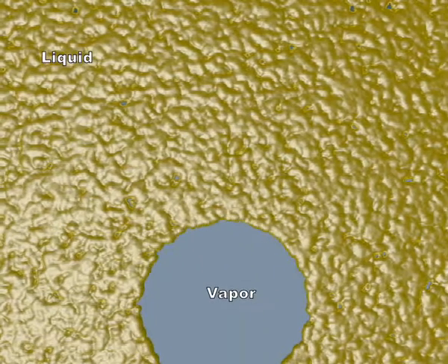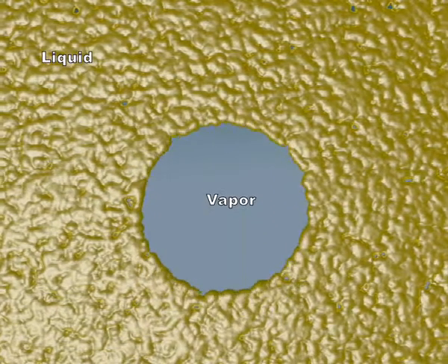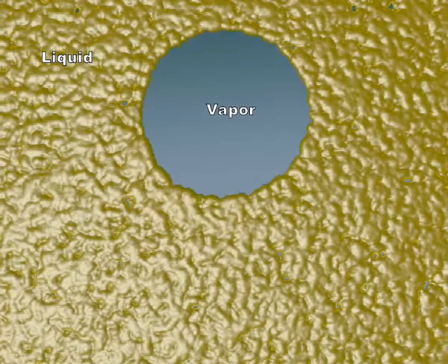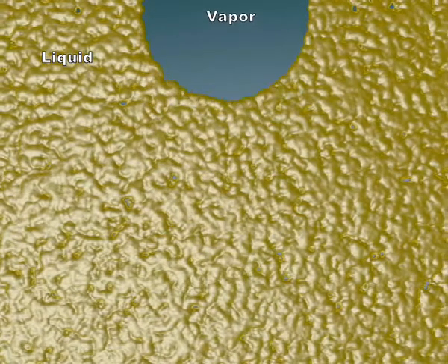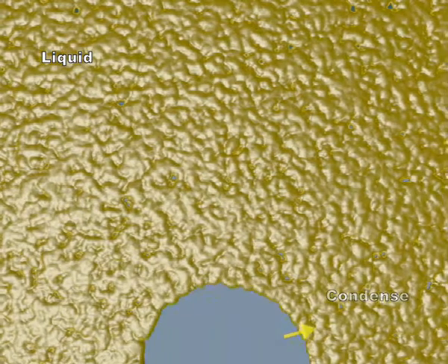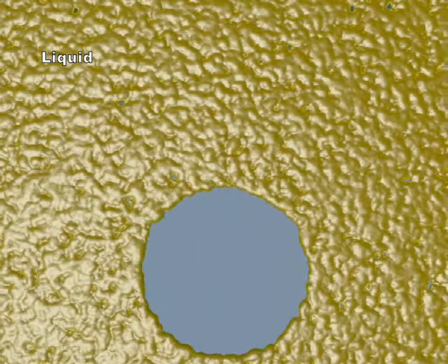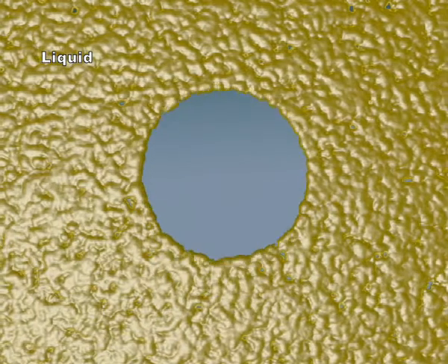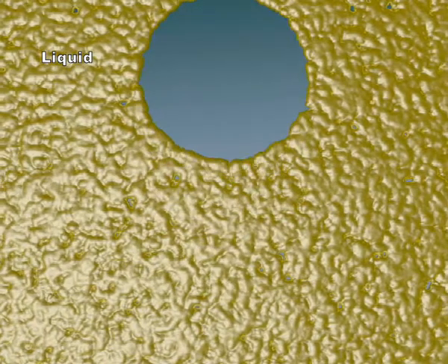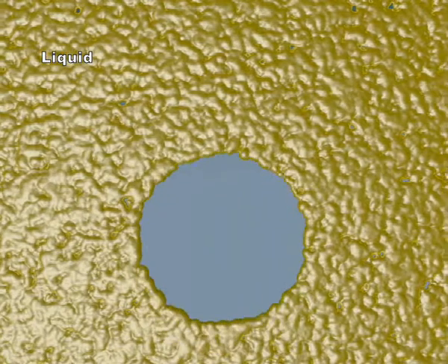The interaction between the liquid and the vapors is vital to proper distillation. When the hot vapor makes its way through the liquid, heat is transferred to the liquid. Some of the vapor will condense as a result and is added as liquid to the tray. At the same time, because of the heat transfer, the liquid will boil and generate more vapors. The continuous contact between vapor and liquid on each tray brings out the separation between components with lower and higher boiling points.